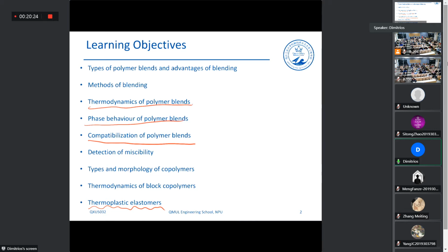The hard phase can be remelted and recrystallized several times because it is essentially a thermoplastic material, while the soft phase is the elastomeric phase, which gives softness, gives elongation to the material, gives low modulus to the material, and so on.